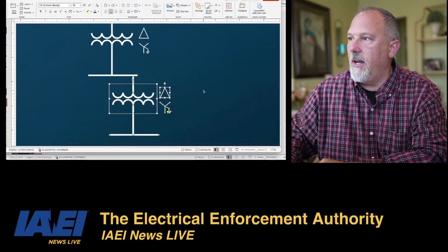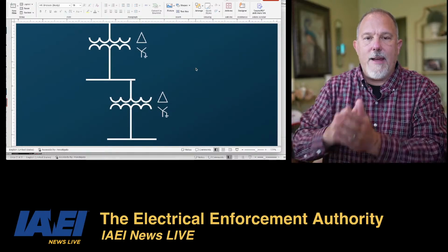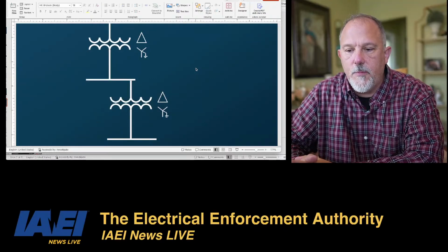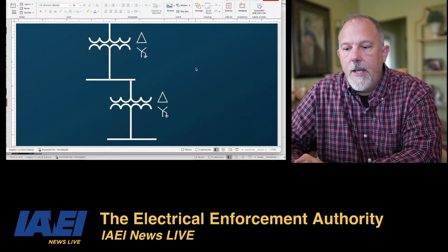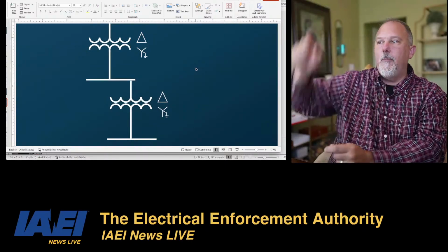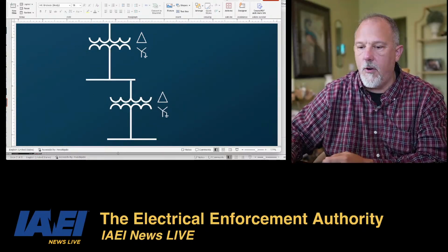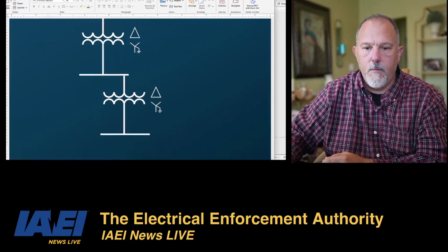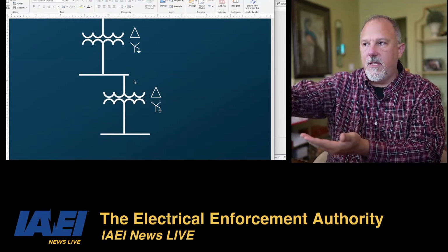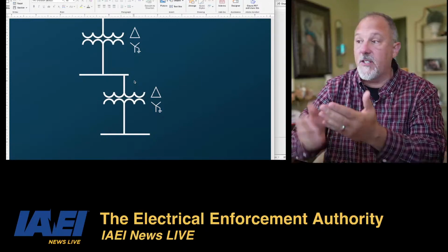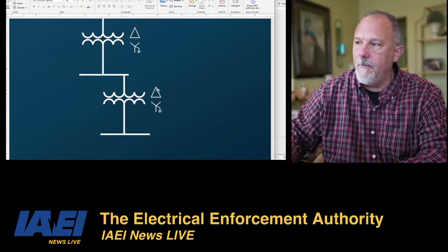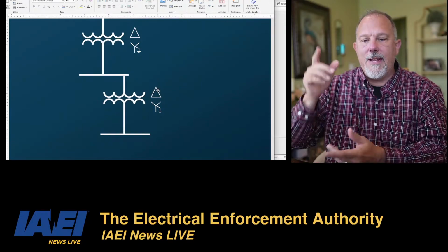Now, Control C, Control V. I can connect another transformer off of that bus. It's not a service. I assume it's on the premises. Delta would be grounded as well, unlike a service. The delta side is not grounded at the transformer, but it is grounded up above. So up here on this system, this panel board is grounded. I only bring 3 conductors to this transformer. I don't need to bring a neutral because there is no neutral, and I would bond everything together. But because I have a delta here, it doesn't mean it's an ungrounded system. What that delta does